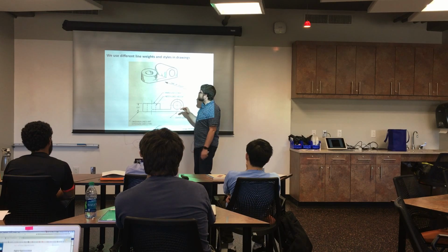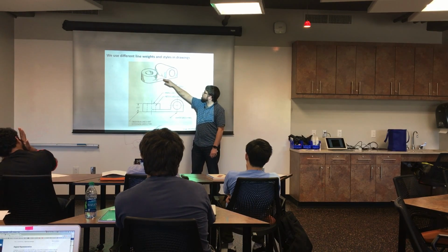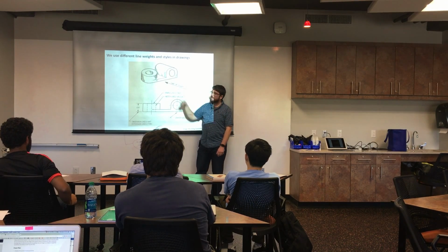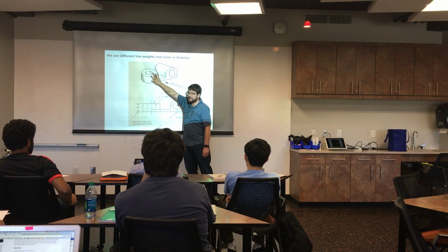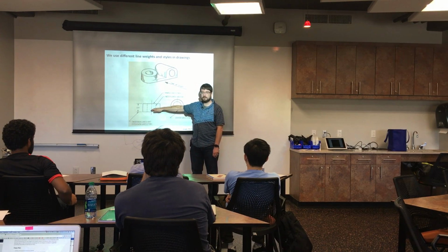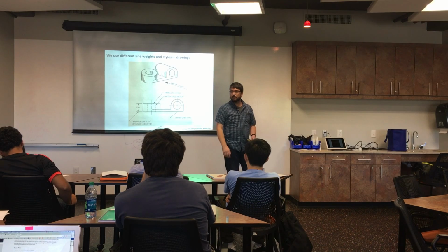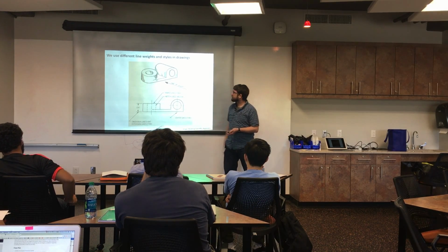So for example, a line where two surfaces intersect might be a little bit thinner than the main outline of the part. A hidden line like these, where this hole, we can't see it strictly in the side view, but we want to notate that it's there, could be dashed, for example. And then the center lines are also generally pretty thin.